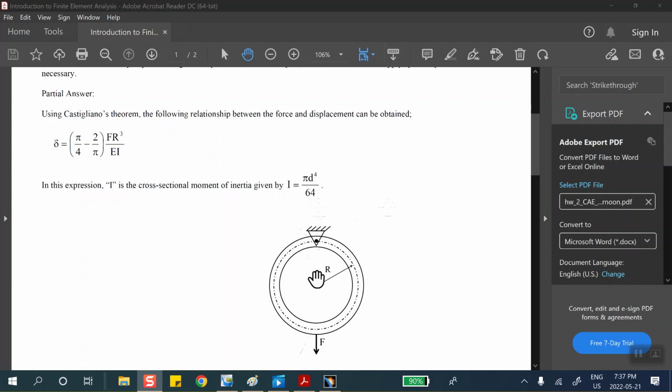First, clamp it, and then of course you have symmetry restraints here, and then pull it down. Then I'm going to go back and start putting a pin here, and you'll see that as you run it, it bombs out several times until you fix it. So first I'm going to clamp it here, although that is not what is shown.